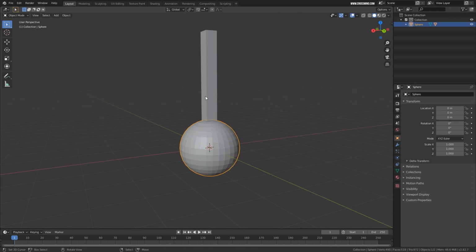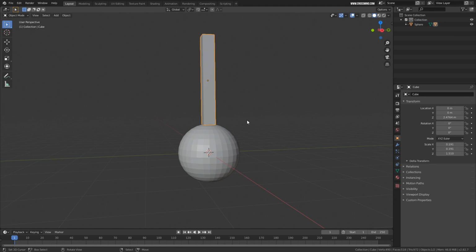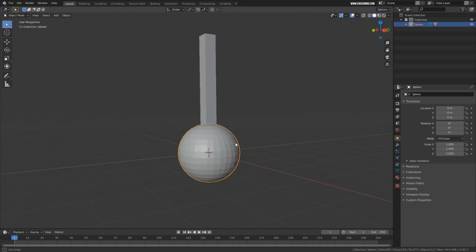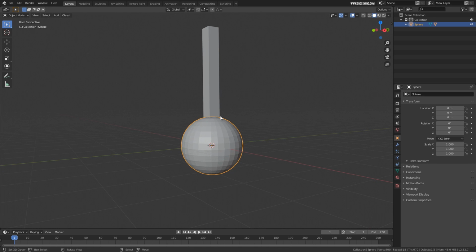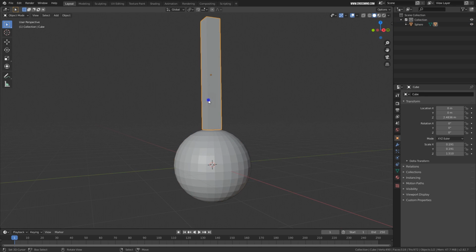I think it's self-explanatory, and whenever you are rigging any complex stuff, this is what you will be dealing with, and the entire rig is designed in a certain hierarchy. So when you're dealing with a human rig, the arms will be parented to the torso, the legs will be parented to the pelvis, and the feet will be parented to the lower legs. The head will be parented to the neck, and the neck to the upper body, something like that. But obviously there will be a much more complex system. So this is what parenting means.